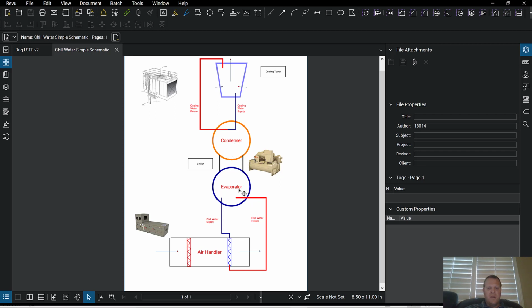It's taking refrigerant that's just made a phase change. It's low pressure refrigerant, and it is going to compress it and put it through something so that it can turn from a high pressure gas to a high pressure liquid refrigerant, right? So the refrigerant's coming from the evaporator side as a low pressure refrigerant gas. It's going to get compressed and go through a condensing cycle here. It's going to try and turn into a liquid. And it needs to give off its heat somehow. It needs to give off its heat, and it's going to go through this cooling tower. So we have this schematic of my cooling tower out here, and I'll talk about it in a second.